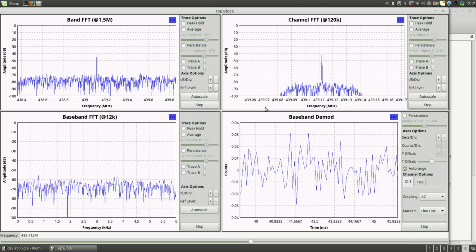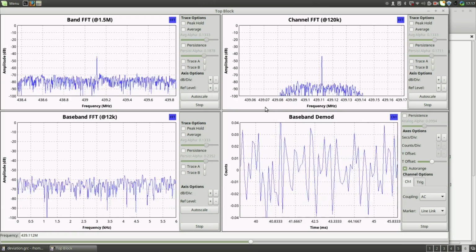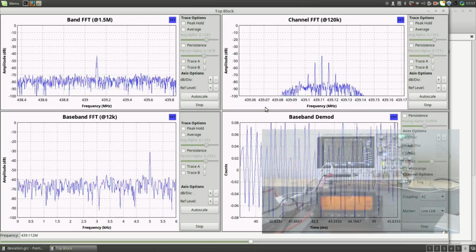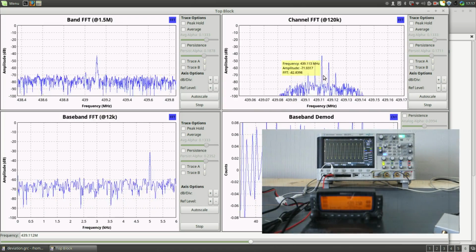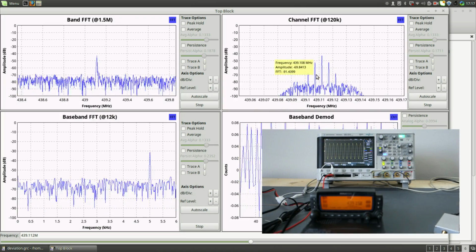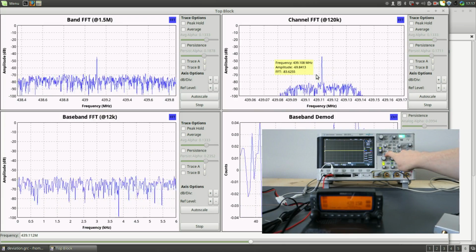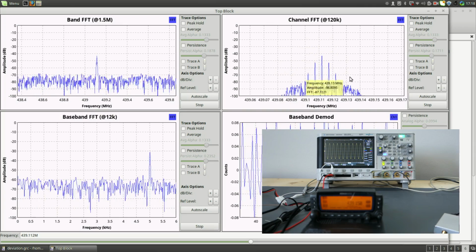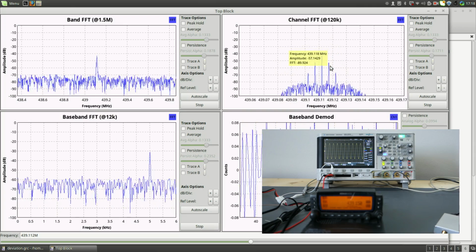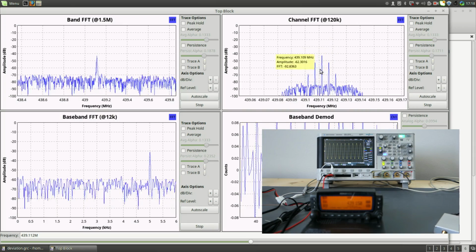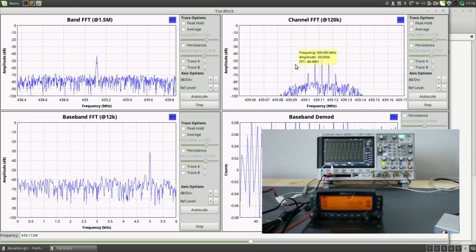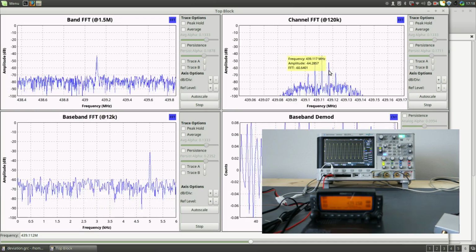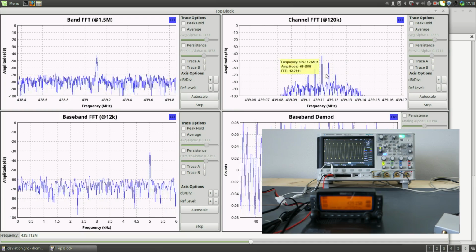So if I turn on the function generator now and feed a 5 kilohertz sine wave into the system, I can see that sidebands appear here. Let me turn it off again, just the carrier, and if I turn it on, I've got 2 sidebands on either side. And these sidebands are spaced 5 kilohertz apart from each other. So if that's the center frequency at 0 kilohertz here, that is plus 5 kilohertz, minus 5 kilohertz, plus 10